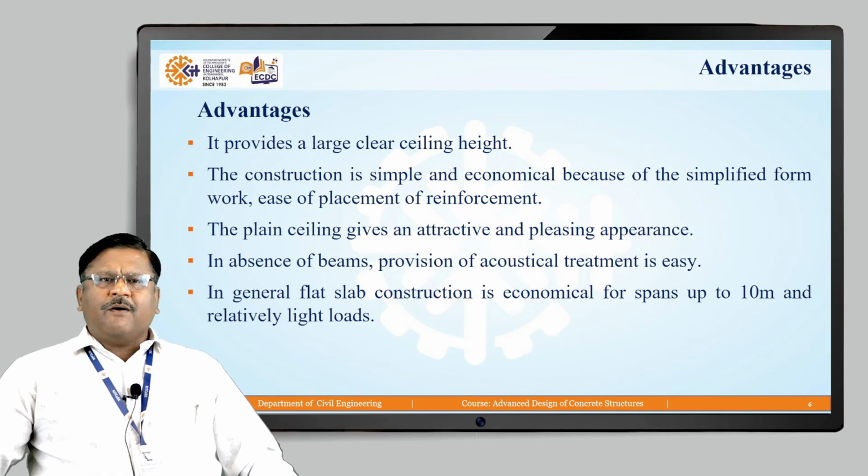Next, what are the advantages of flat slabs? The following are the advantages of the flat slab. First, it provides a large clear ceiling height. Second, the construction is simple and economical because of simplified formwork, and it is easy to place the reinforcement. Third, the plain ceiling gives an attractive and pleasing appearance.